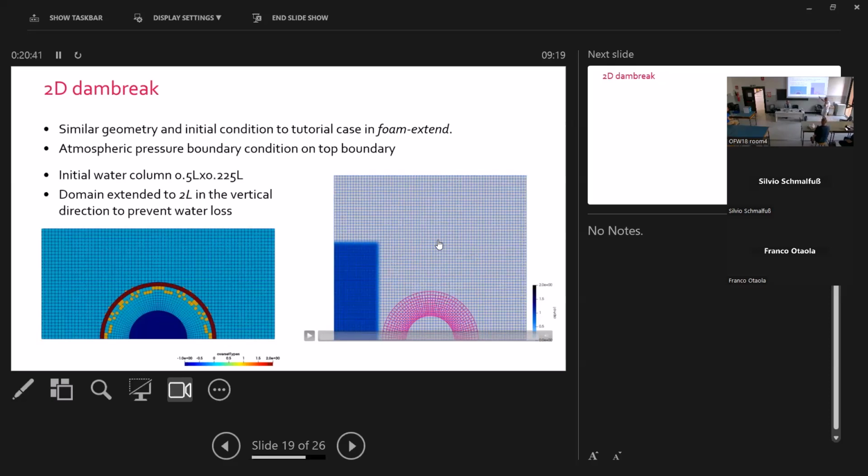So yeah, the free surface is very complex. What I do want to do when I'm here is do it on a Cartesian grid. And the other thing is, I didn't show it here, but in the overset, because there's no mass conservation, you also get bubbles formed in the fluid phase, which we don't have.